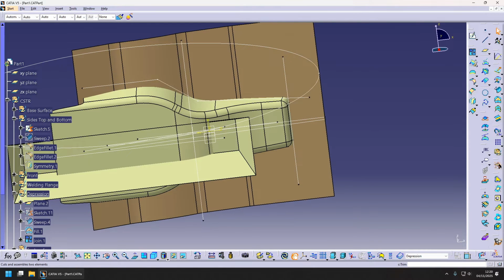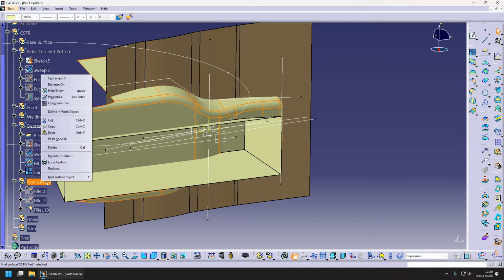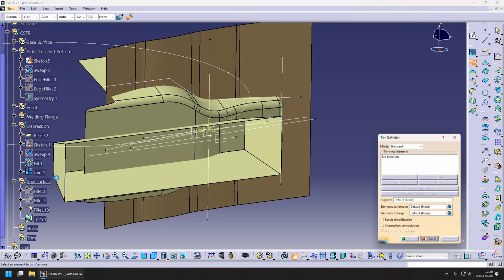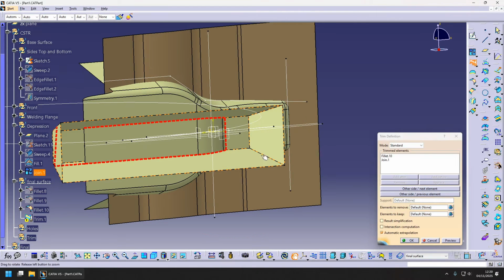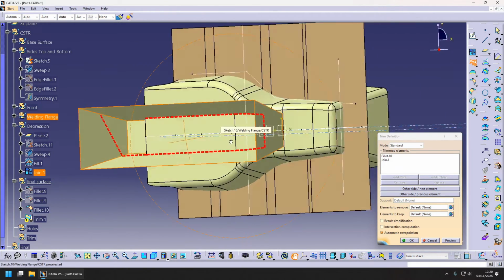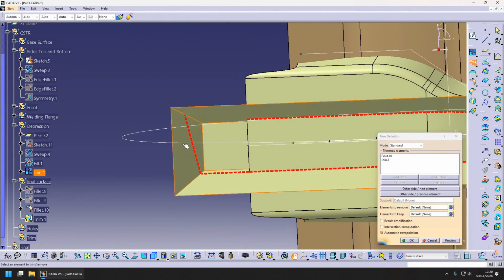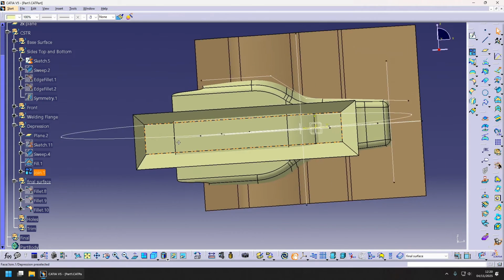And now for a very nice operation, we do a trim. But before we do that, we go to the final surface, and we're gonna trim this surface that we generated here with this depression here. And you see it doesn't work for some reason. Okay, the reason is because this one doesn't intersect this. That's how trim works. It's a little bit fiddly.